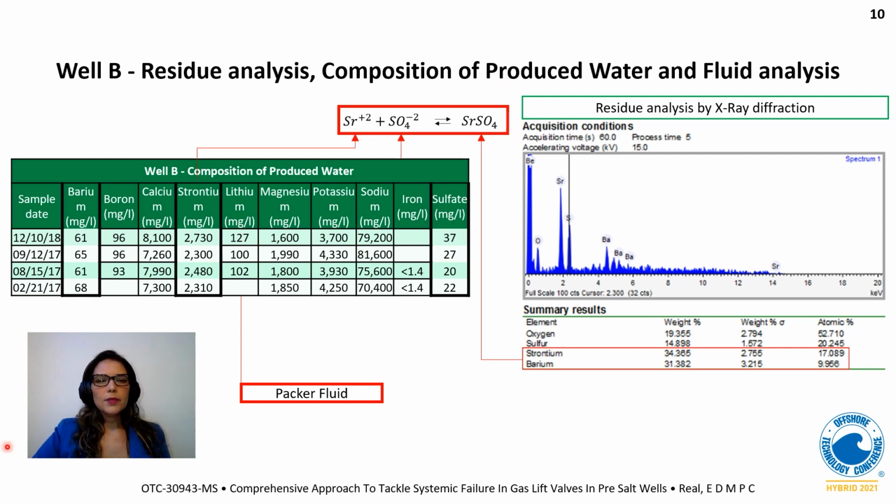In a high pH system, such as the completion fluid environment, the reaction is enhanced. The same is true for the formation of barium sulfate. The saturation index reached a high value, making a suitable condition for scale deposition.